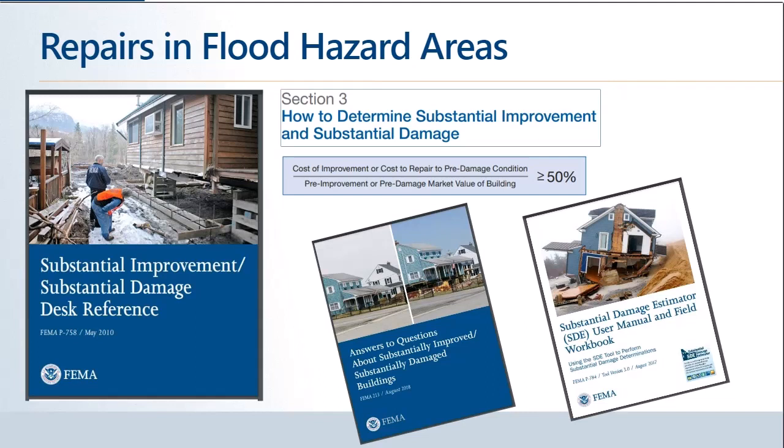found in some documents put out by FEMA, at least the minimum requirements. And keeping in mind that the local communities you're in, and their enrollment in the National Flood Insurance Program, may and sometimes often do adopt more stringent requirements, most often consisting of a lower threshold, 25%, 30%, 40%, and they're incentivized to do so as they get improved premiums on their flood insurance program by adopting more stringent compliance provisions. So knowing exactly where the trigger falls and some of those specific requirements is a local dive, but the minimum ones put out by FEMA are some of the ones we're going to talk about moving forward.